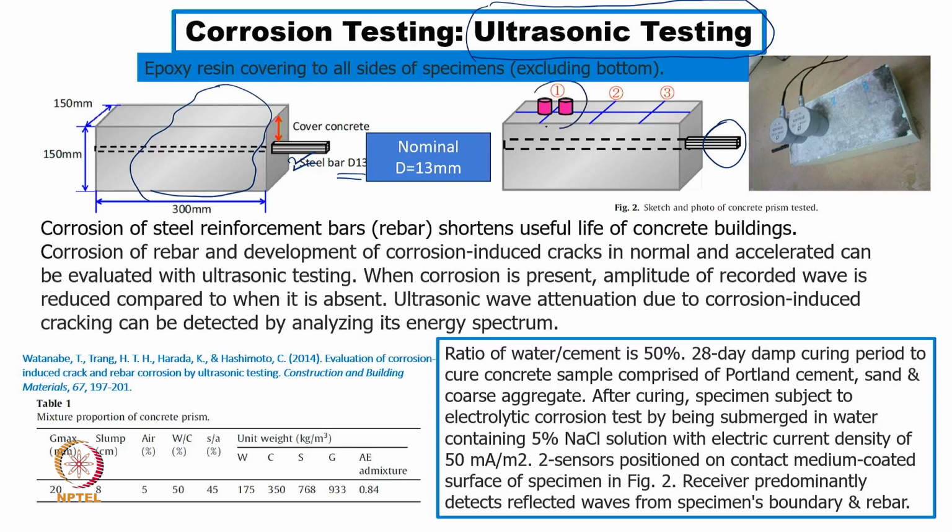And then we are showing here the two sensors to send ultrasonic waves, and collect those ultrasonic waves back, and then predict what is really happening. Is there any subsurface crack? On the surface we do not really require sophisticated equipment, but for the subsurface we really require sophisticated equipment, because we know today a subsurface crack is there. It will lead to the surface, maybe after a few hundred cycles or a few thousand cycles, and then that kind of failure will be a catastrophic failure, damages will be more, and we want to predict everything well in advance.